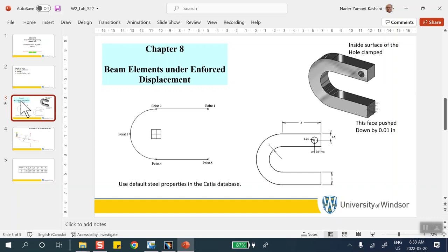Now, I want to remind you that Catia's FEA package does not give information on the stresses in a beam. The only piece that it gives is kind of useless. It gives axial stress, principal stress, that's totally useless for us. The reason is that when you talk about beams and stress in them, you have to tell me where in the beam. Is it this location, top fiber, bottom fiber, neutral fiber? So to get a plot for you, it kind of becomes meaningless perhaps. Some other software do it, but then they decide where they're plotting the stresses, the contour of a stress or anything like that.